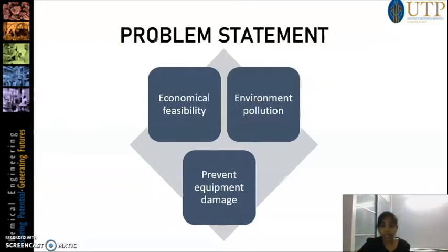To be more precise, for instance, CO2 which is saturated with water could lead to damage of processing equipment. This is because it is highly corrosive, especially when it is saturated with water. It could also decrease the heating value, resulting in solidification in chillers or refrigerants.